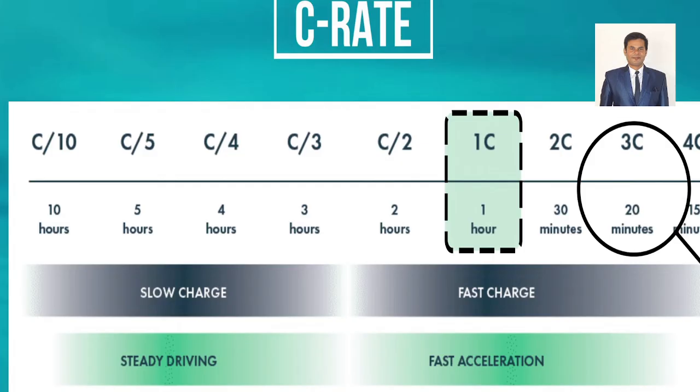That is how much charge can be stored in a specific time limit, right? These are the various examples I have given so you understand clearly: fast charging, and the steady state driving force of the charges, that is the slow charging, right? If you see the 4C, the time is very less. It is charging in 15 minutes. That we call very fast charging, right? On the left hand side there is C by 10. For the same amount, an electric vehicle will take a very long time to charge, because of the steady driving force and the slow charging rate of the batteries.